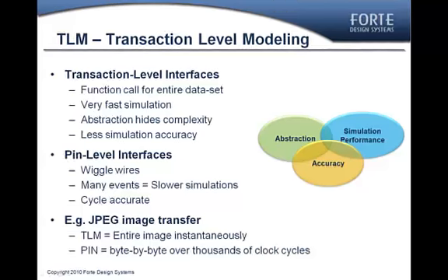TLM is another acronym that often causes confusion to the SystemC newcomer. TLM stands for Transaction Level Modeling. This essentially refers to how we move data from one place to another and depends on what kinds of interfaces we use between blocks. When writing design modules in Verilog RTL, you are transferring data from one block to another using what we here at Forte would call pin-level interfaces. This involves wiggling wires in detailed protocol implementations.